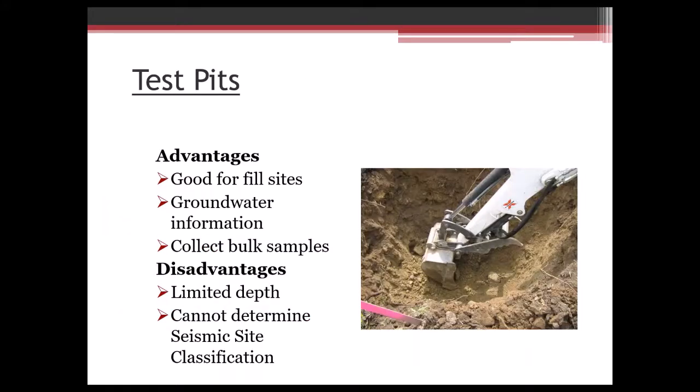Another method we have to get subsurface soil conditions is test pits. Test pits have a lot of advantages. They're really good on fill sites. If we're trying to investigate whether or not the fill is able to be reused and/or how bad it is, sometimes it's hard to see how bad the fill is with the boring.